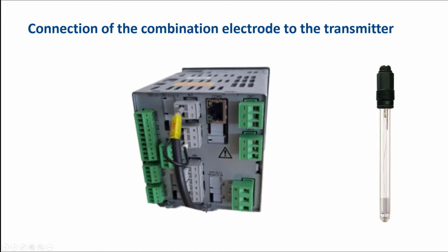The figure shows the connection of the combination electrode to the analysis input 1 of the Jumo Aquis Touch P multi-channel device. The inner core of the coaxial cable carries the potential of the measuring system, the shielding that of the reference system. The standard wiring shown corresponds to the asymmetrical connection. This requires a factory-fitted short-circuit bridge.